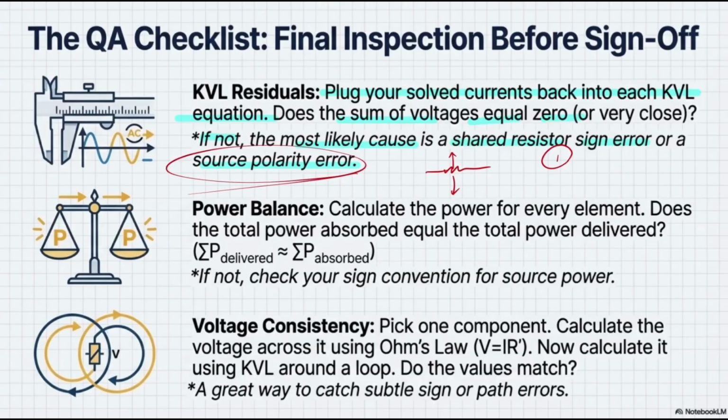In some questions, when we do have 2 sources, both in one direction and both inside the one mesh, you have to subtract them. If one of them goes from negative to positive and the other from positive to negative, you have to consider that it would be better to take one of them as your reference as positive and make the other one negative.